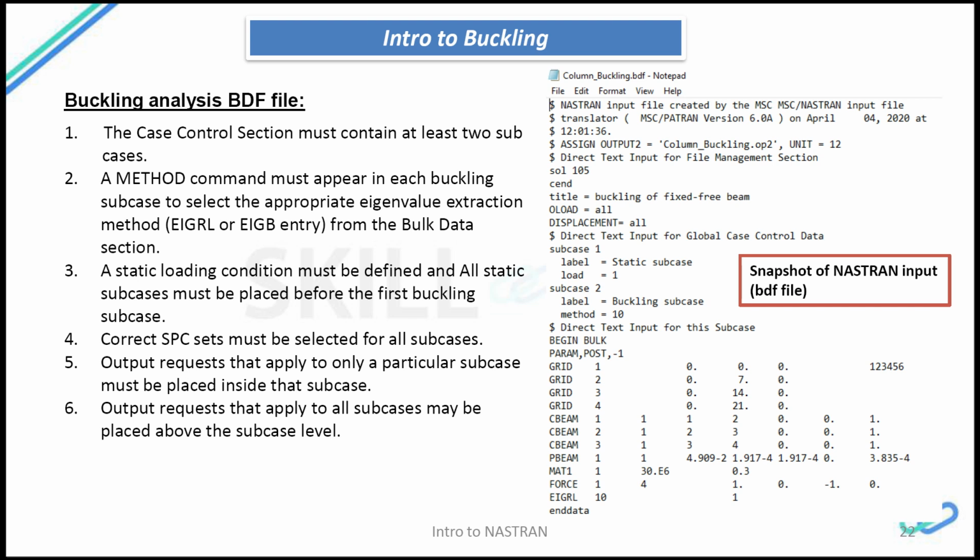That is automatically placed if you generate the BDF file from Patran, or if you write your own BDF file, then you have to place the static subcase before the buckling, because the solver solves for static before it goes to the buckling.